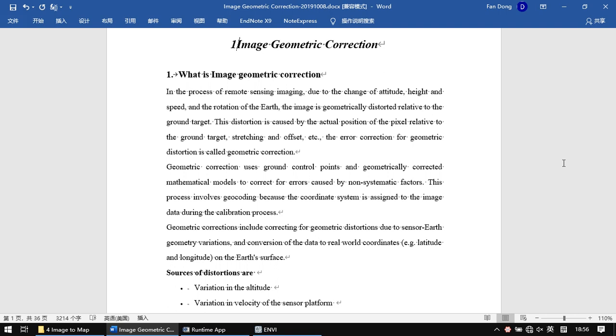We learned three geometric correction methods: the image geometric correction based on the position information of sensors, suitable for MODIS level 1 data; the image geometric correction with GLT file for FY3 data; and image-to-image registration for Landsat data.